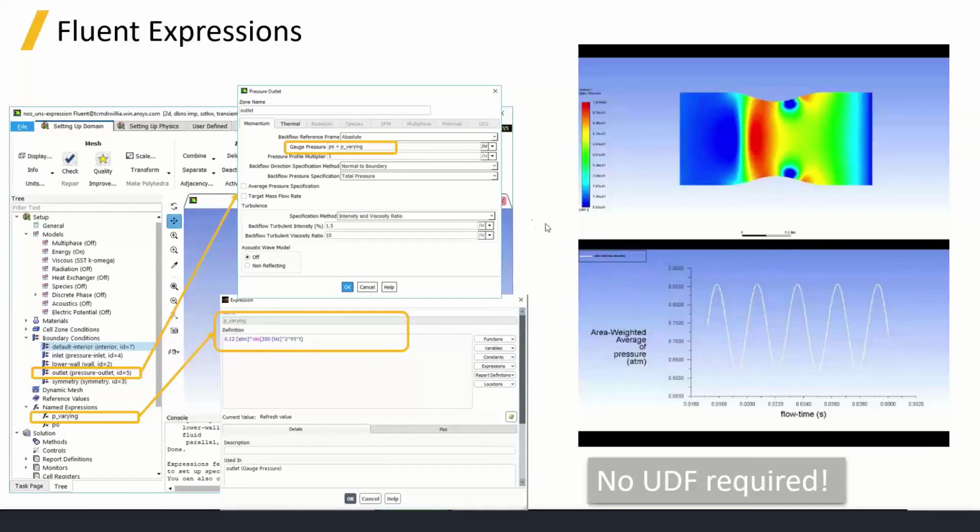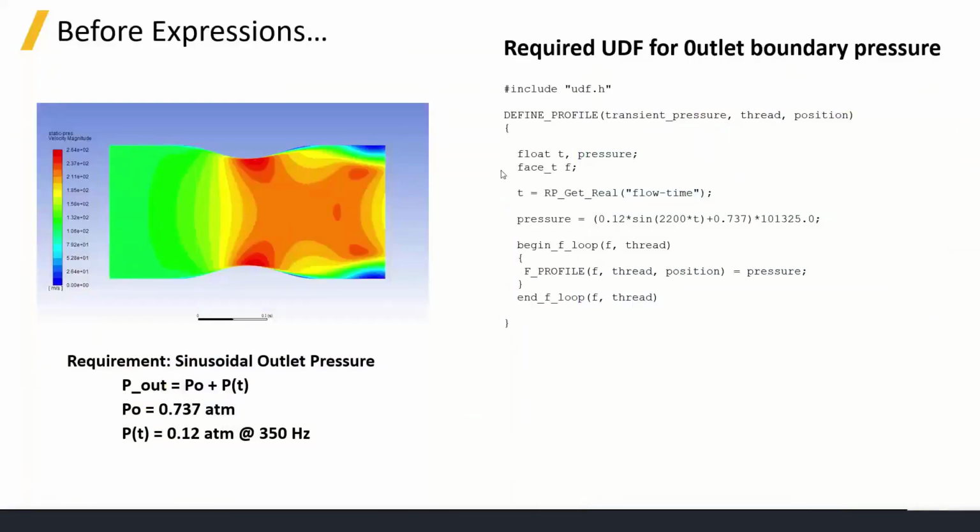The nice thing about this is there's a lot of diagnostics we can do on the way. We can actually plot this as a function of time before we even start to make sure that all our units and things have come together. Also, we can make sure that we've got consistent units, which if we just go back to that UDF, it's up to us to make sure this is all giving us units that are in the SI system.